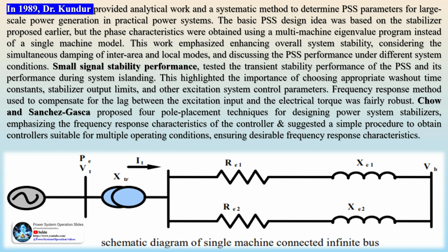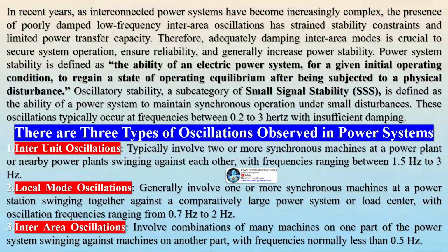In 1969, DeMello and Concordia explored the stability of synchronous machines under small perturbations by examining a single-machine infinite bus (SMIB) system through external reactance. Their analysis provided insights into the effects of thyristor-type excitation systems and established the stabilizing requirements for such systems. These requirements included the voltage regulator gain parameters and the transfer function characteristics for a machine speed-derived signal, along with the voltage regulator reference to provide damping of machine oscillations.